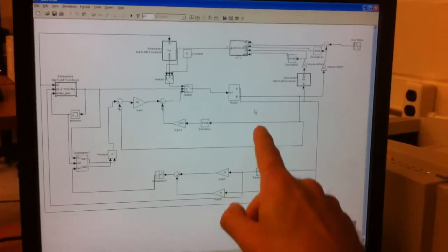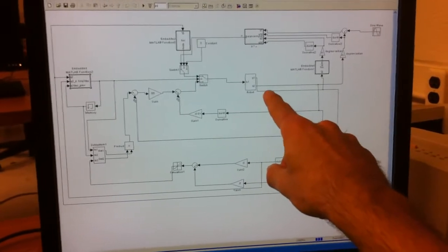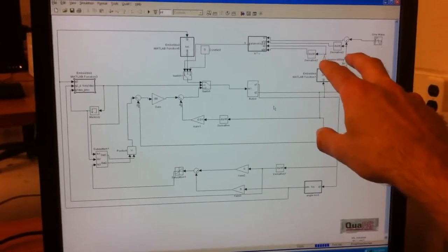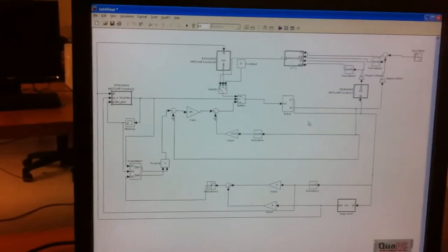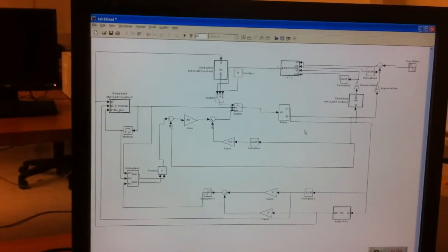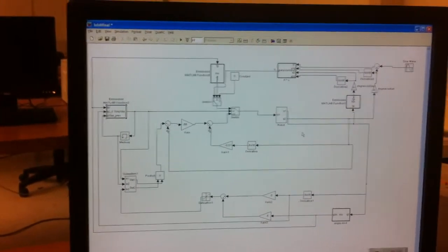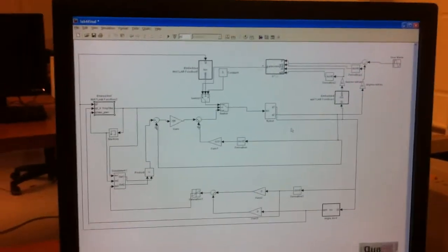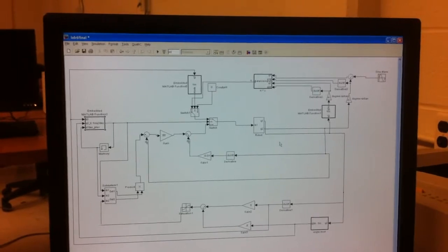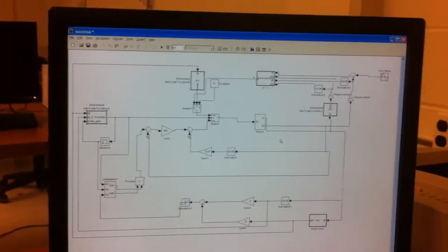And so you can see for this control system, we take Q1, which is the angle of the rotor, and we take Q2, and then we also take the derivative, so the joint velocities, and once we had the linearized state space version, we calculated the gains, which we multiply each state by, in order to get our voltage input that will control and balance the pendulum.